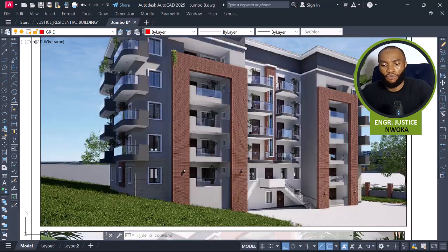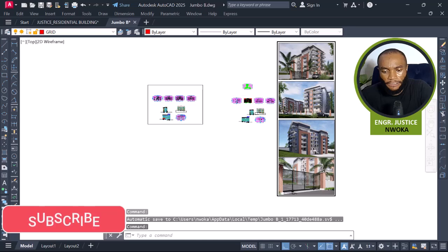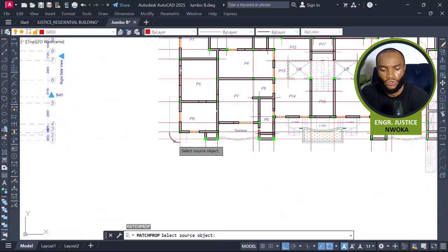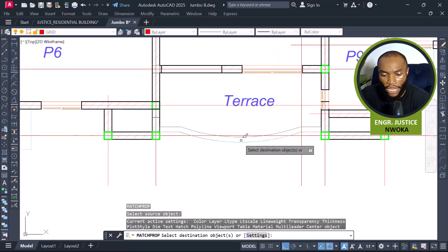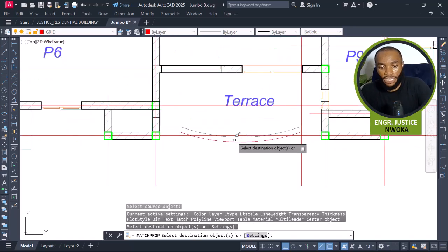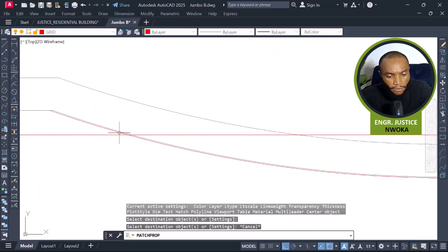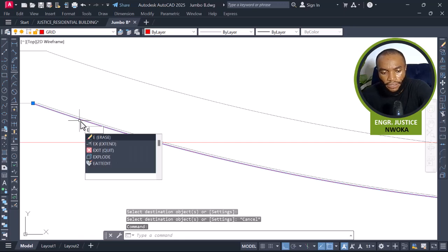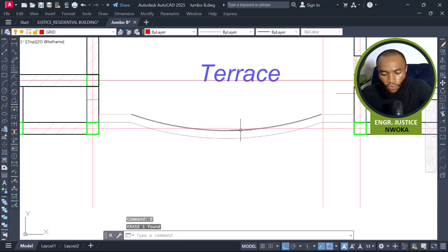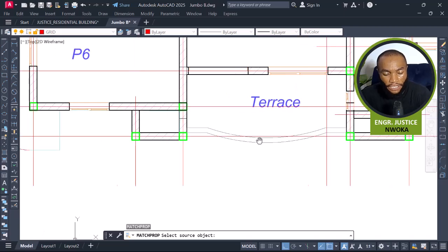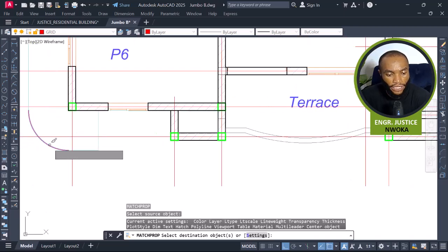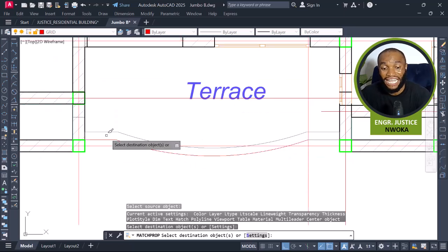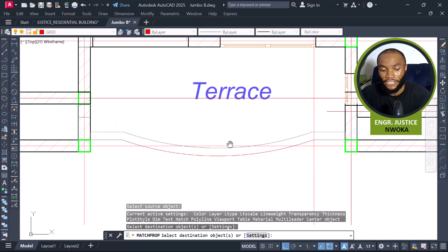So with that now, let's go back to this, and the same principle applies. Convert all your curves to grid lines. Okay, grid lines. There are two curves here. Remove one first. Remove this, sorry, and take the main one, which is the one you're seeing right now. So come now, click on this and convert this. This now becomes our slab edge. Okay, our slab edge. This is a straight line.